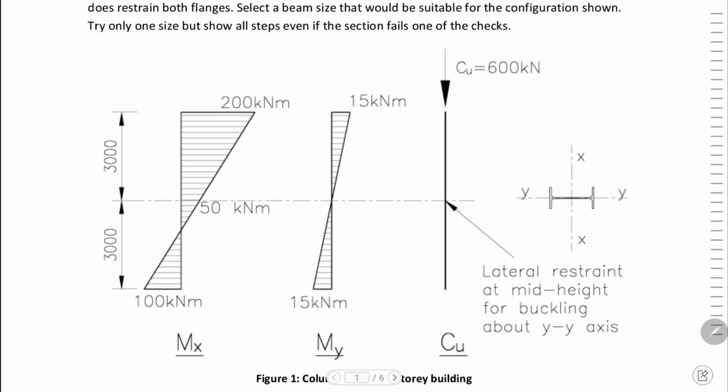bottom. Now in reality, bending about both axes is actually the exception rather than the rule. In most structures you design it for bending about one axis and then you brace it in the other axis, so you'll have a portal frame and the likes. So it is unusual to find biaxial bending, but it does sometimes happen, especially in industrial buildings, unless you have unusual structures and unusual loads where you can't